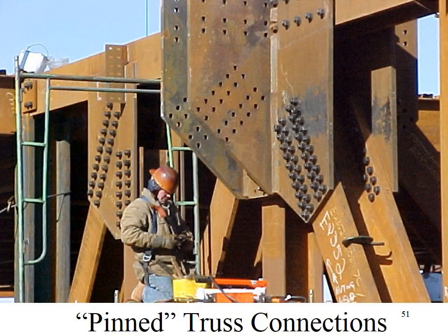This is a pin connection. Does it look like a pin? Not really, but that's how it was designed. This is a truss that's supporting 35 stories of a 38-story building in Boston. All the members are 14 by 500-pound members. They all have on the order of 4,000 kips in them. The gussets that you see there are 2 inches thick. The bolts are A490, 1.25" diameter in oversized holes, slip critical class B. Is that a pin connection?